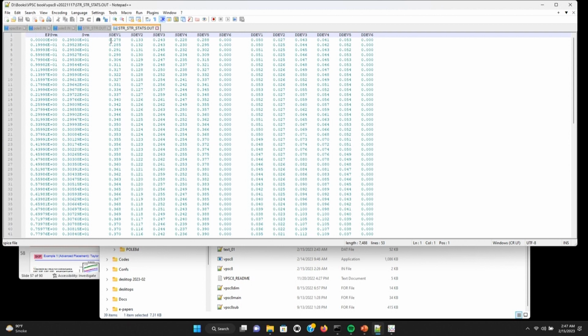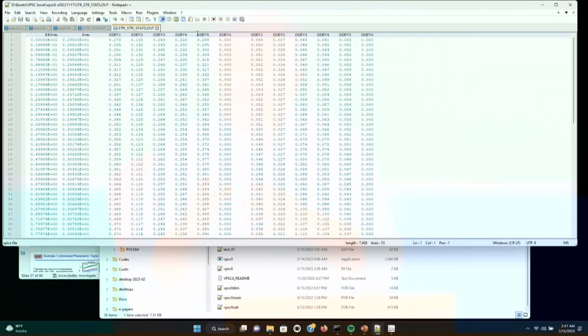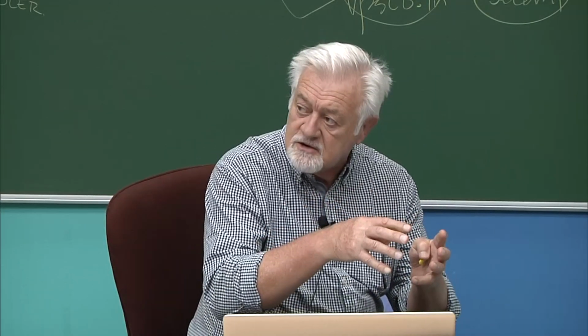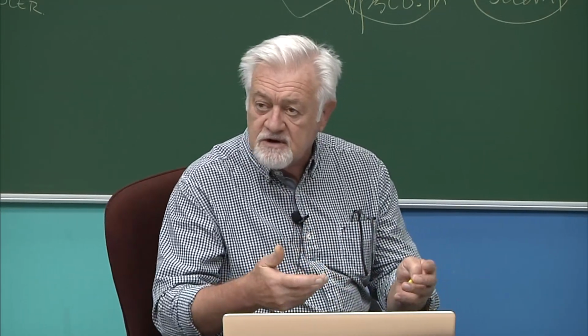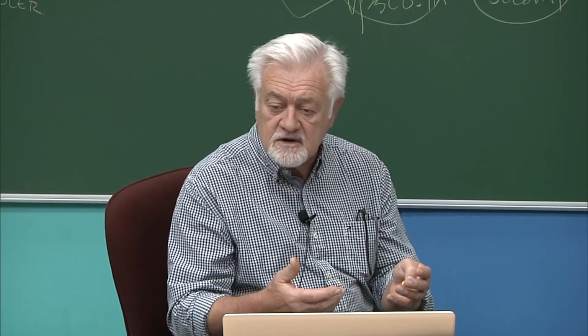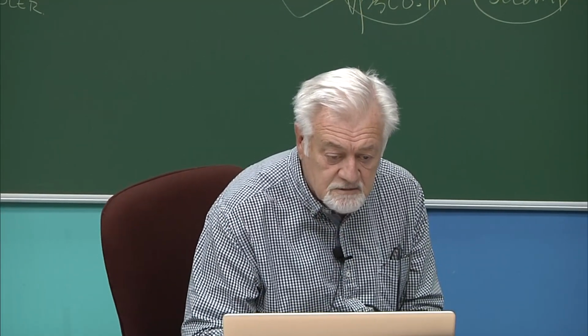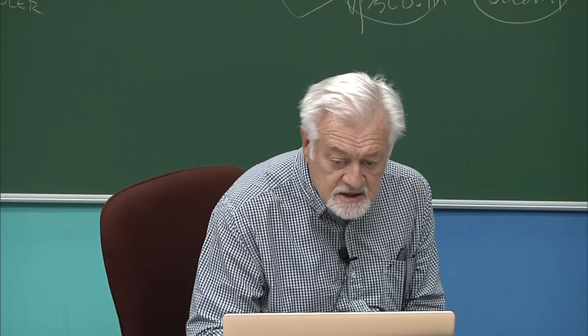But you can calculate the standard deviation among all the grains, and that gives you an idea: if you have a very narrow distribution in the strain and a larger distribution in the stress, it means that you are closer to the upper bound. You are closer to the Taylor problem. The other way around, if you have a large deviation in strain, but the stresses have a narrow distribution, then you are closer to the Sachs bound.